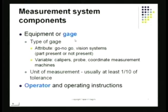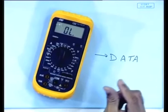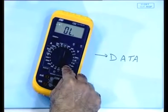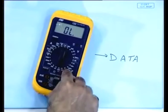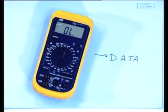The first source of variation could come from the gauge itself. When I take the same gauge and use the same part, let's say some voltage coming out of a battery, and I try to measure that in the system here, the gauge and the method of measurement may introduce some variation, and that is what we call gauge error or repeatability error. If I repeat my readings, I will find there is some variation in it. This is due to the gauge itself. A single person making multiple measurements will end up with that variation, which is the measurement variation.